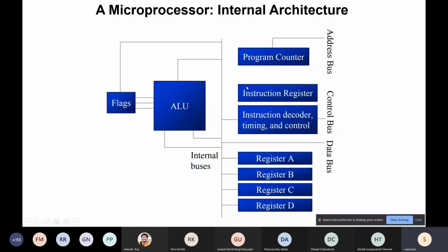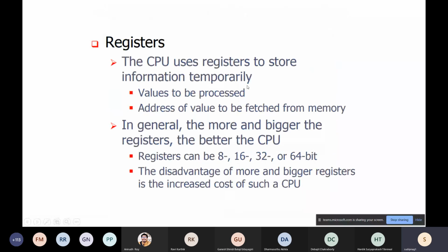So registers are something like SRAM, as I said, and it can be of different widths based on the microcontroller. Sir, either 8 or 16. Yeah. Tell me, do 8-bit AVRs have pipelining? Yes. AVR is a RISC microcontroller.